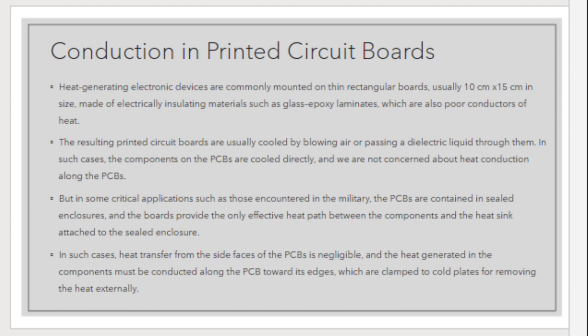But in some critical applications, such as those encountered in the military, the PCBs are contained in sealed enclosures, and the boards provide the only effective heat path between the components and the heatsink attached to the sealed enclosure. In such cases, heat transfer from the side faces of the PCBs is negligible, and the heat generated in the components must be conducted along the PCB towards its edges, which are clamped to cold plates for removing the heat externally.